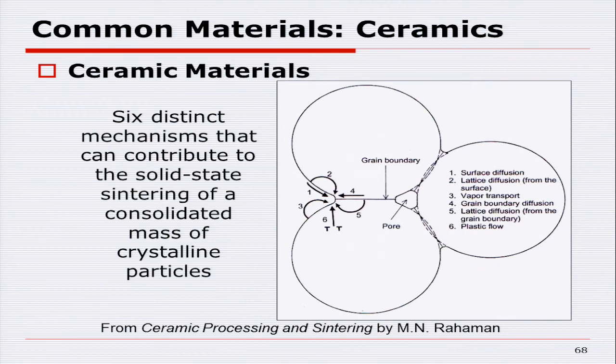And that glaze has a lower melting point. And we can get lower melting points by putting additives in, such as lime. And that lowers the melting point, so we've got what's called soda lime glass, by the way. Glass is made the same way in that we mix ingredients up and we heat it. But in the case of glass, we make everything melt. But we want to keep the melting point low, so we add different substances to it to drop the melting point down.